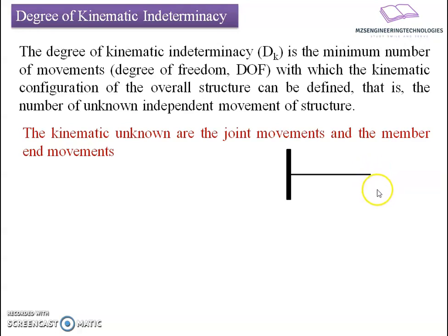So this will have degrees of freedom which will be multiple in number. For example, if a vertical force is going to act, it is able to move in the vertical direction, means it will show deformation in the vertical direction, so there is a degree of freedom in the vertical direction. If I have an axial force, then it may have extension in that direction. It will have a degree of freedom in the horizontal direction. If it is subjected to bending, it will show flexural displacement here. Thereby degrees of freedom will be counted here, and it may be subjected to twist at the end, and distortion will be observed with reference to torsional forces here.